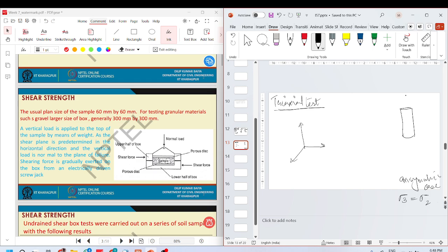The stresses in the directions will be sigma 1, sigma 2, and sigma 3. When you take a sphere, all the stresses will be the same. When you take a cylinder, then the stresses along this axis will be different and the rest of the stresses will be the same. This makes our problem easier because now we have to deal with two principal stresses instead of three.